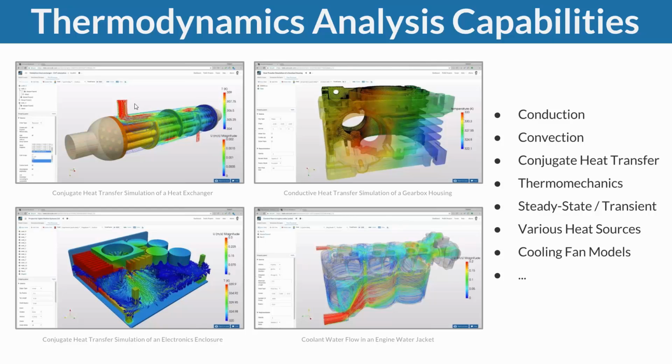So we have a fluid entering the domain at a specific temperature, and then the heat transfer coefficient between fluid regions and solid regions is automatically computed. So it's simulated, not constrained. And then the next step is that within the solid, heat transfer is also computed, and so ultimately you end up with a temperature field across solids and fluids, and the heat transfer coefficient between them is computed.